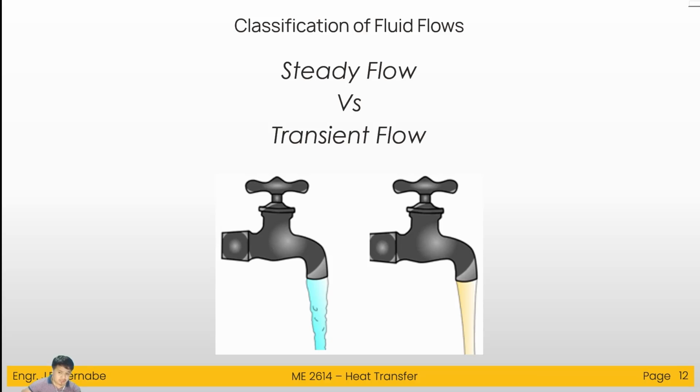It will be steady. So that is the difference between steady and transient flow. And usually transient is associated with initialization. Compare this with unsteady. Sometimes unsteady is used interchangeably with transient, but actually they are not really the same. Although they have similarities, transient flow is usually used for initial flow. Unsteady is literally unsteady, anywhere in time it could drastically change. But anyways, this is just terminology. We can use them interchangeably in this very simple context.